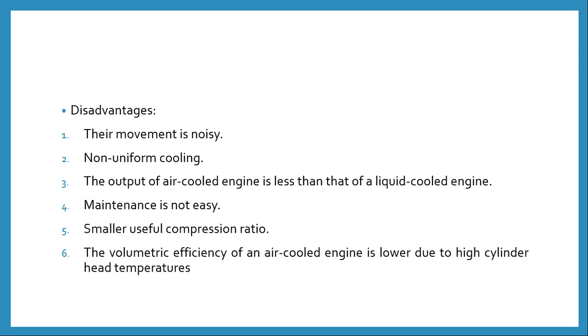The useful compression ratio and the volumetric efficiency of an air cooled engine are lower due to the high cylinder head temperatures. An air cooled engine cannot provide uniform cooling all around the engine cylinder.